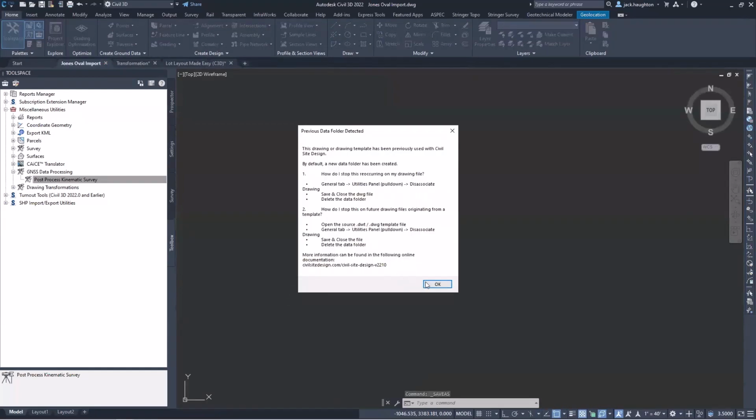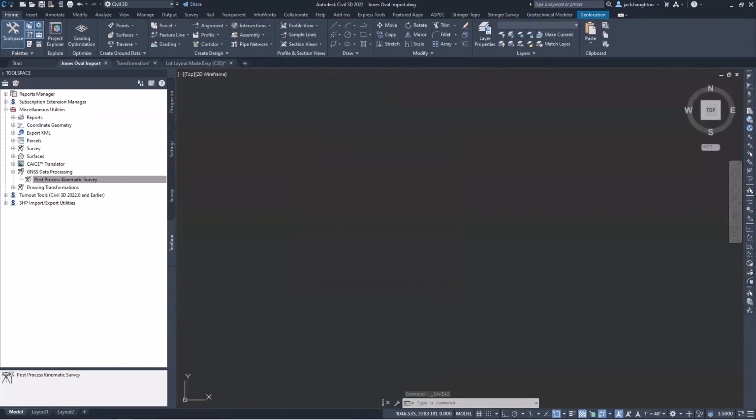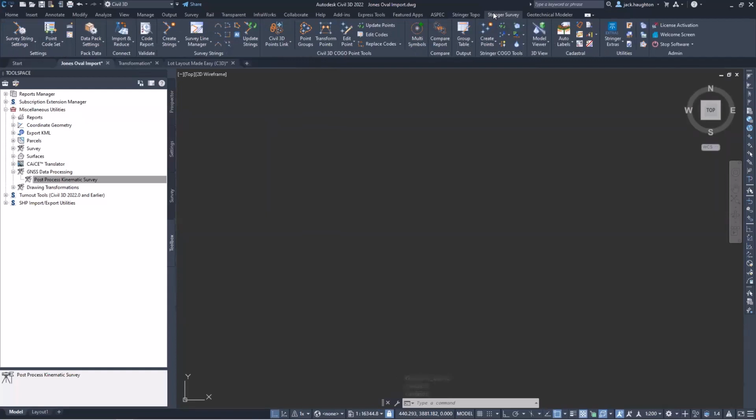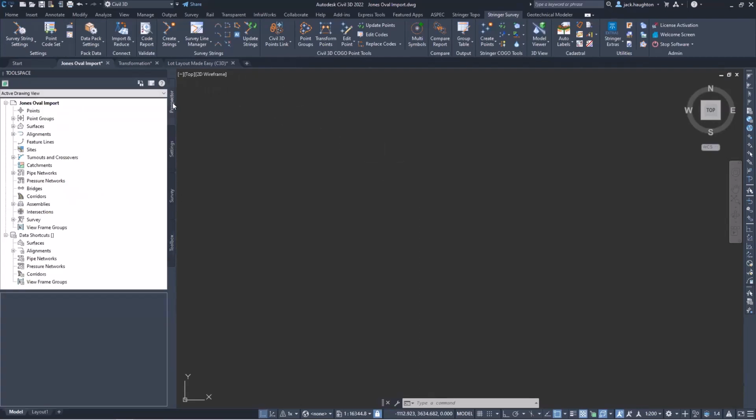Now, let's get into bringing in a raw observation file, what I'm sure a number of you are here to see. Now, what we're going to want to do is just select this tab here, and then we want to bring in our file. Before we do so though, we just want to have a look at our settings, because I showed earlier how to get the point information in, how your point is going to look, all that information in using the description key set, again, found under settings, point, and description key set.